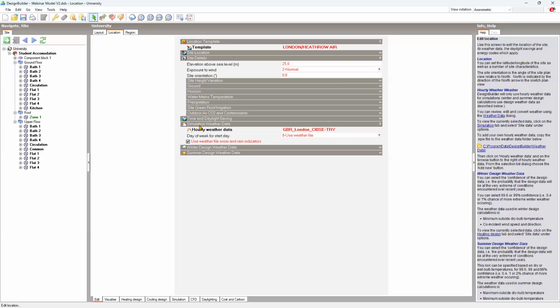So an appropriate weather file specific to your building location should be used. For building specific projections, if more accurate weather data is available for a nearer weather station in a climatically similar location, then you should use that in the baseline projections.